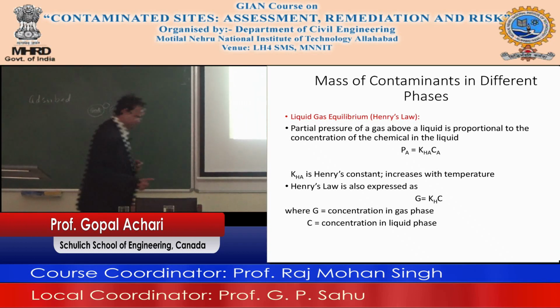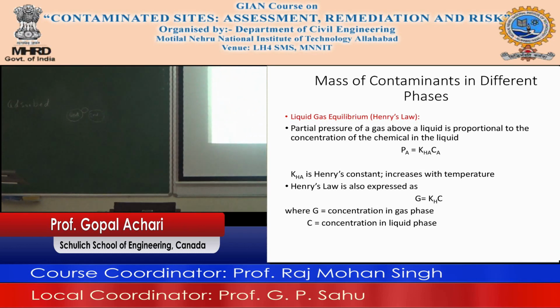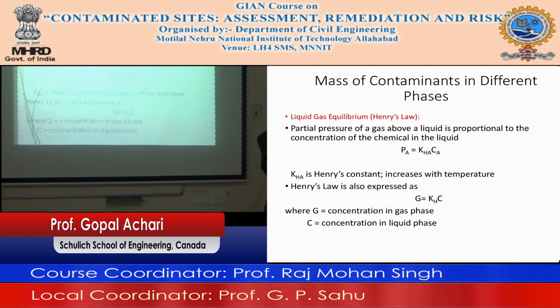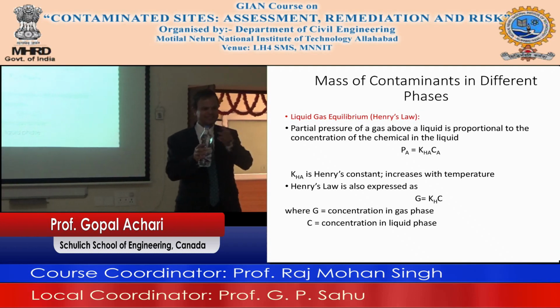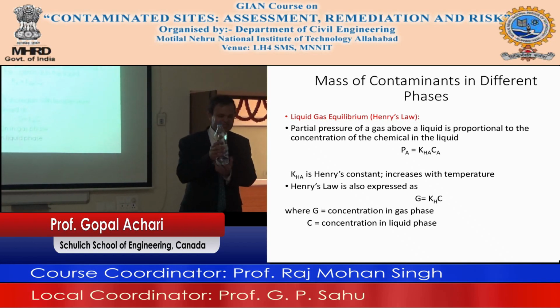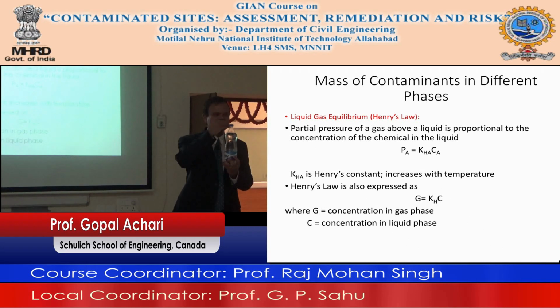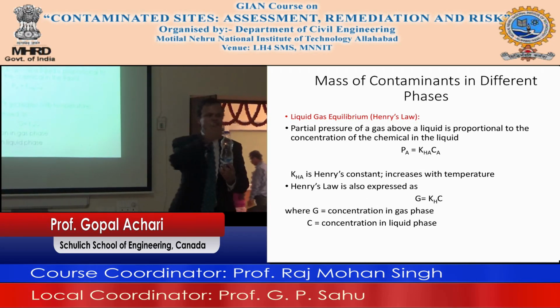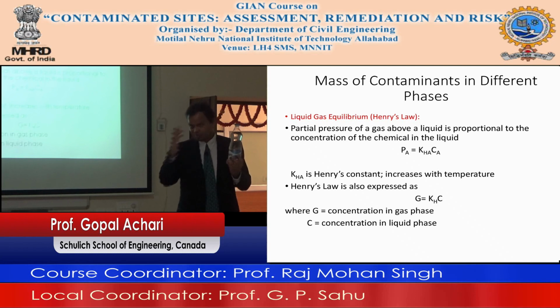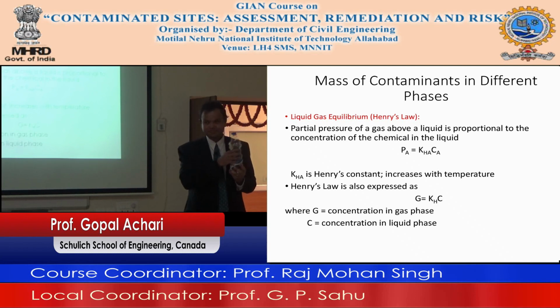So coming back, if I take this air, I have no way of removing the benzene. I take this thing out, I run a fan over it, get rid of the air. What's going to happen? The benzene will move from the liquid phase to the air phase, and if I take that air and replace it with a fresh batch of clean air, benzene will move from here to there. And benzene will move from here to there. Eventually the benzene concentration in the water is depleting. Okay, it's a slow process, it is depleting, right?